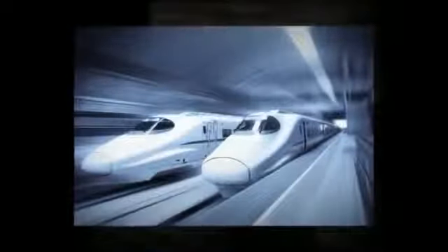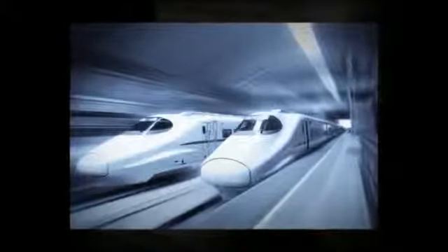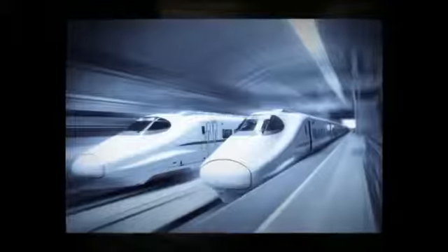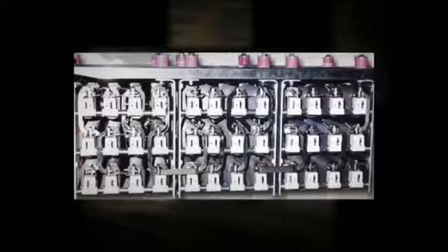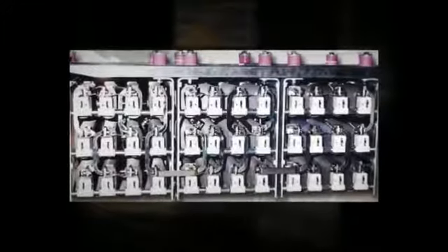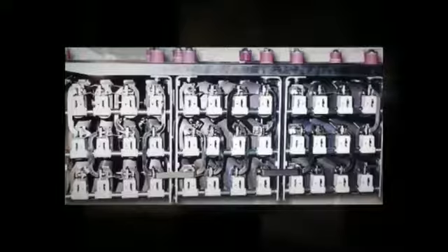For example, while a locomotive train is coasting, the engineer, using a controller similar to a throttle, energizes the traction motor field, causing the motor to act as a generator. The resistance of the motor field helps slow the train. The electric current generated by motors in dynamic braking mode is dissipated as heat in banks of resistors.